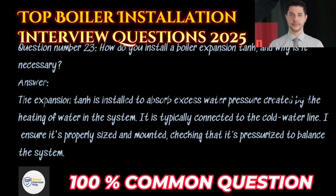Question number 23. How do you install a boiler expansion tank, and why is it necessary? Answer. The expansion tank is installed to absorb excess water pressure created by the heating of water in the system. It is typically connected to the cold water line. I ensure it's properly sized and mounted, checking that it's pressurized to balance the system.